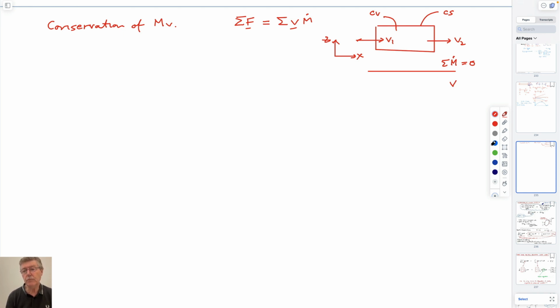So in terms of this diagram, what are those going to be? Mass flow rate is into the system, so this velocity would be negative. Mass flow rate's out of the system, so this mass flow rate would be positive, because it's the V dot N times rho A is this term. But in terms of velocity, velocity 1 is in the Cartesian direction, so this is positive, and this one is also in the positive Cartesian direction.